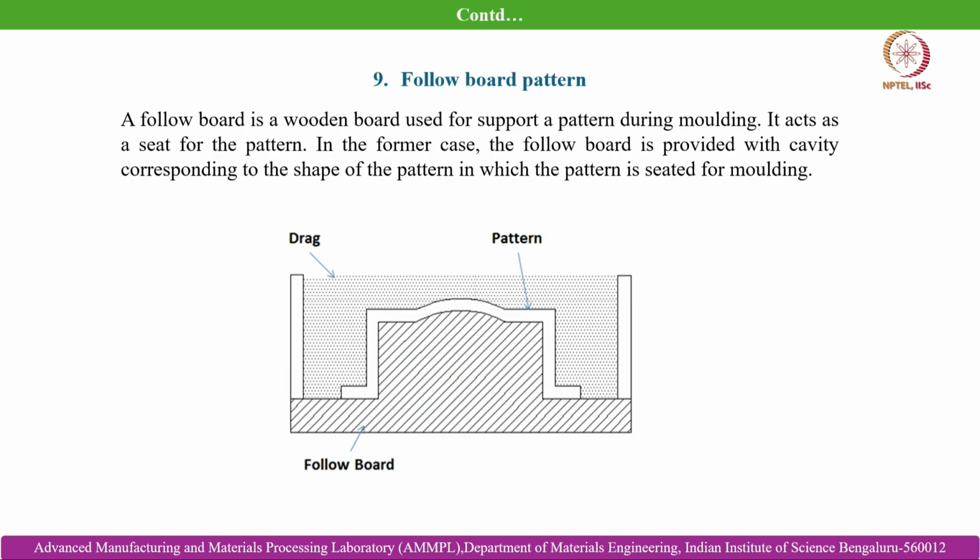And then there is the case of the follow board pattern. A follow board is a wooden board used to support a pattern during molding. It acts as a seat for the pattern. In the former case the follow board is provided with a cavity corresponding to the shape of the pattern, in which the pattern is seated for molding. So, where is this follow board pattern useful?